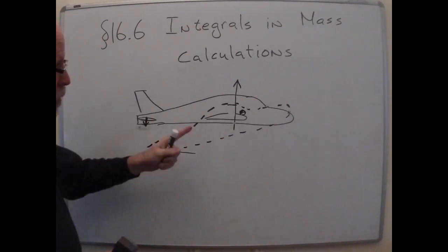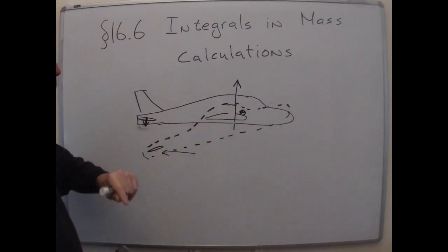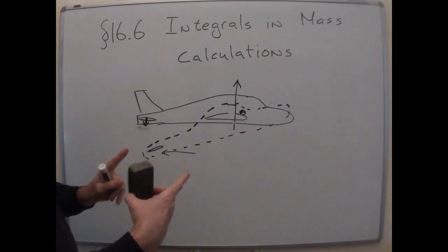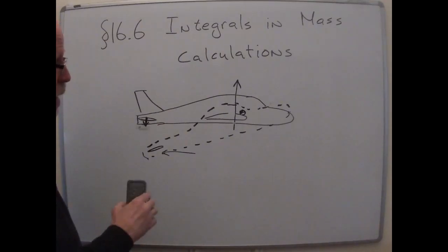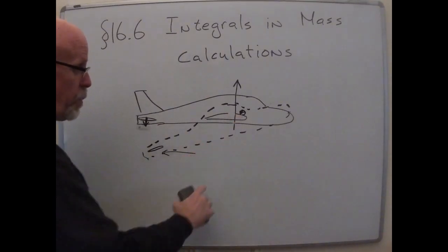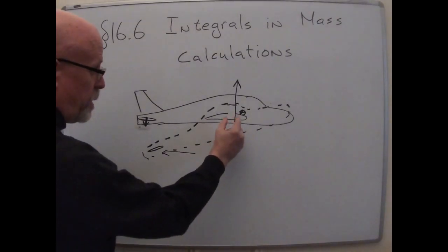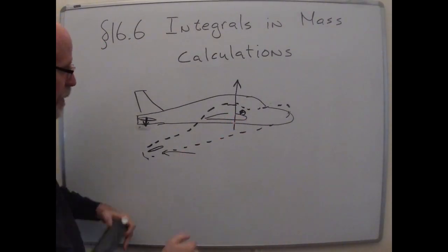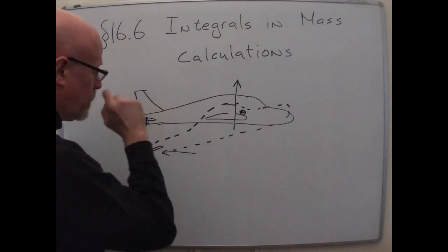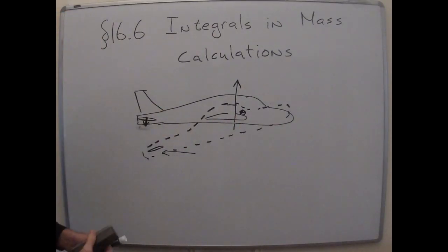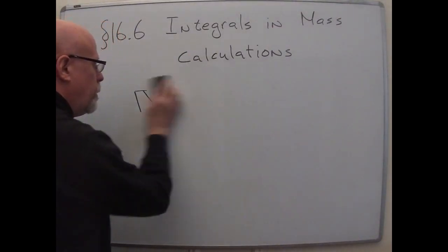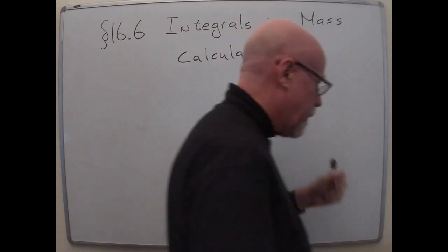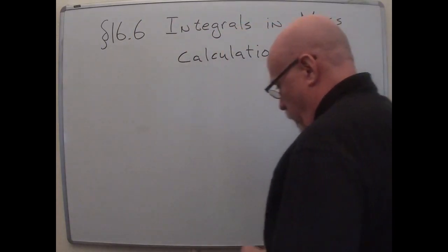You don't want to be in that situation. So pilots routinely calculate the moment arms and they're told what the moment arms are, and then they supply the masses and do a calculation to make sure that the center of gravity is where it belongs. It needs to be within about 10 inches probably of a particular location. But if it goes too far off, it can be hazardous. Okay, so how does anybody calculate a center of gravity?